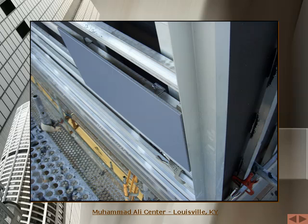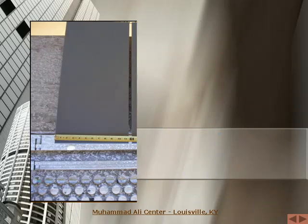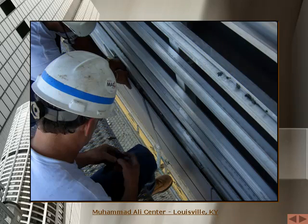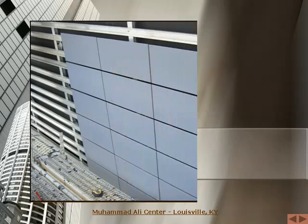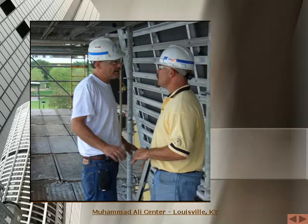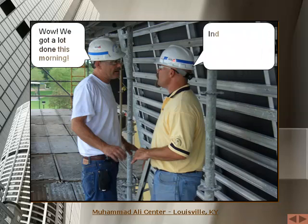This system allows for effortless adjustments of tiles along the horizontal railings should it be needed. Workers check the spacing of the tiles. This design calls for a 1/2 inch gap between the tiles. Workers begin installing the ceramic tiles onto the horizontal rails at the specified spacing. This system provides a clean, finished appearance with no visibility of the fasteners. Even the installers have positive comments about this system.